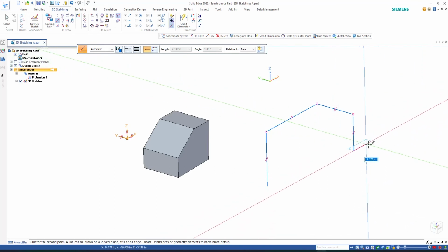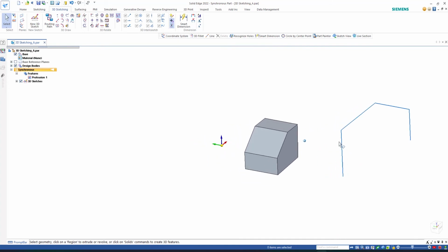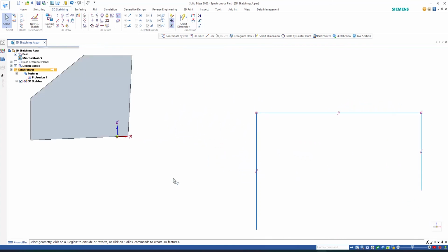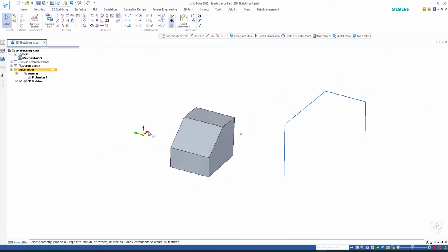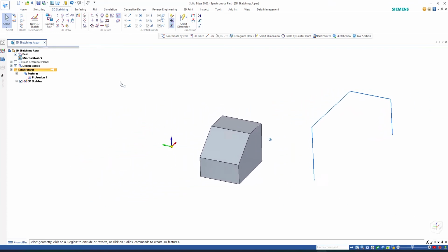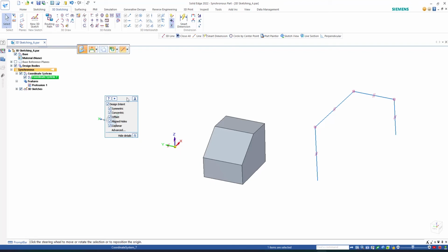However, in some cases, you want to kind of create your own. Obviously, this basically works on the origin there, right? Kind of snaps into those orientations there. But sometimes you need to create a different orientation. So what you need to do is create a coordinate system. And I'm just going to place one right there. Doesn't matter.